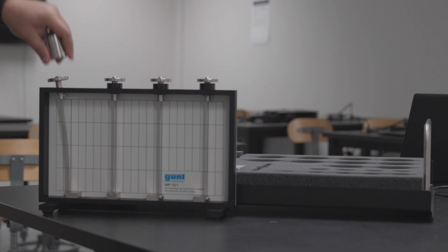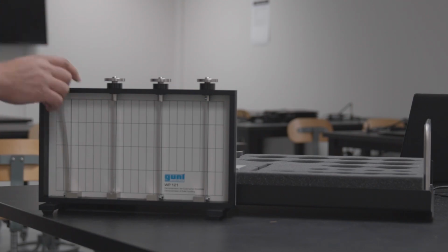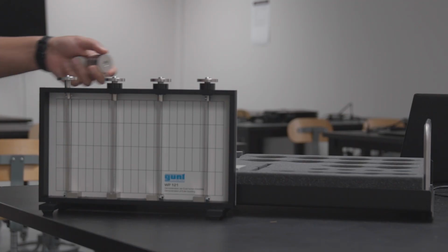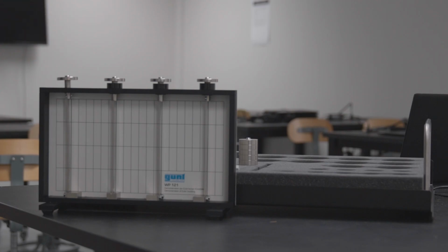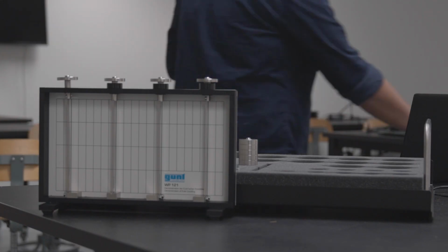You record this load and move on to the next support, right? And then when you have recorded this, I'm going to do the rest of the columns as well. But when you record the 4 Newton load, the next step would be to take the measurement of the column, which can be done with a caliper.